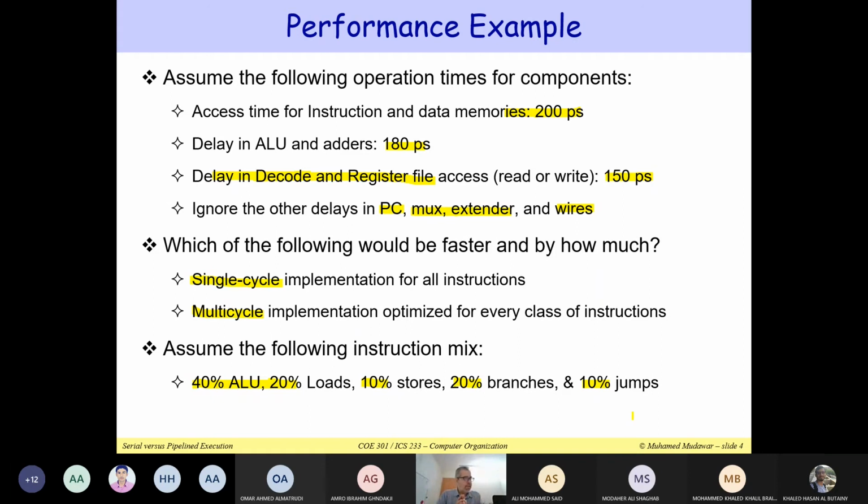So by introducing registers, you can do the instruction in multiple cycles. You can break it down into multi-cycles, and at every step you can put the result in a register. So what is missing are registers, but these are internal registers inside the CPU. And finally, once you have computed the final result, you can write it back into the register file.